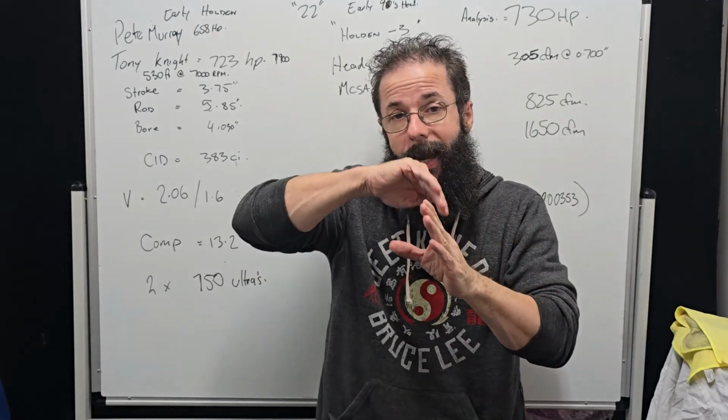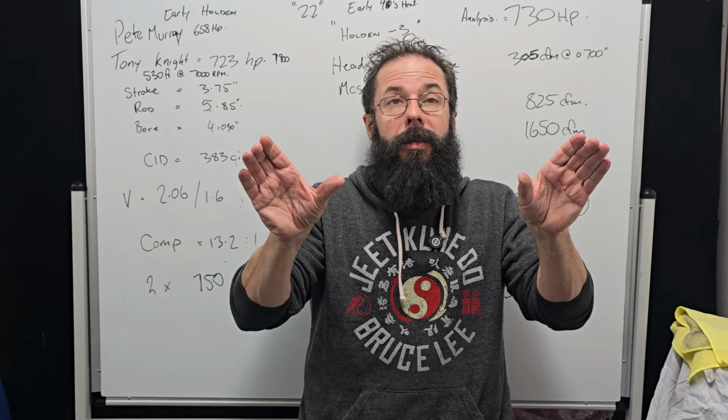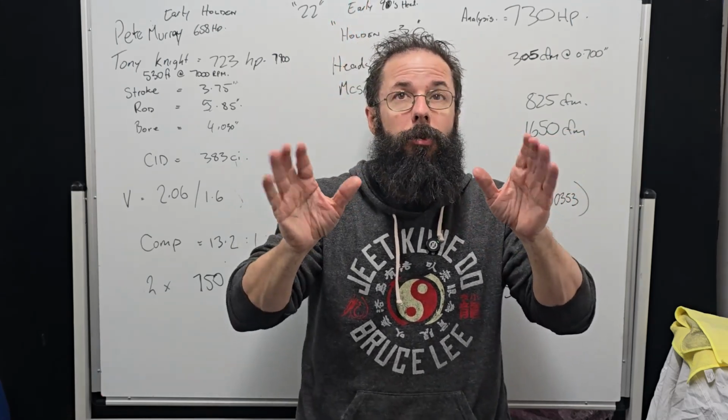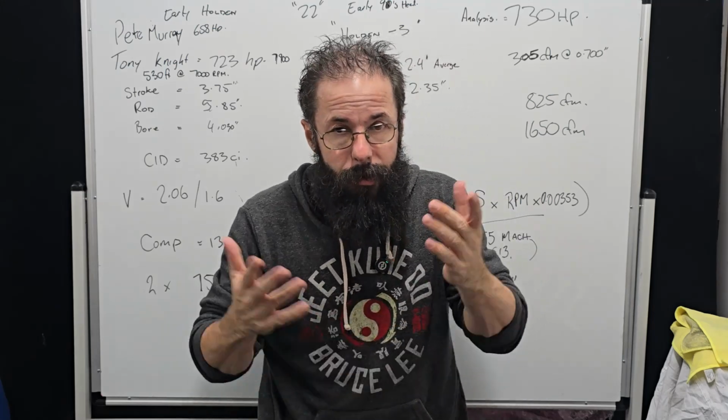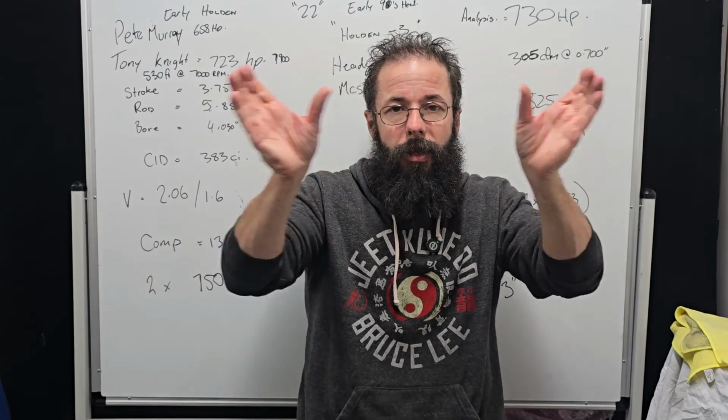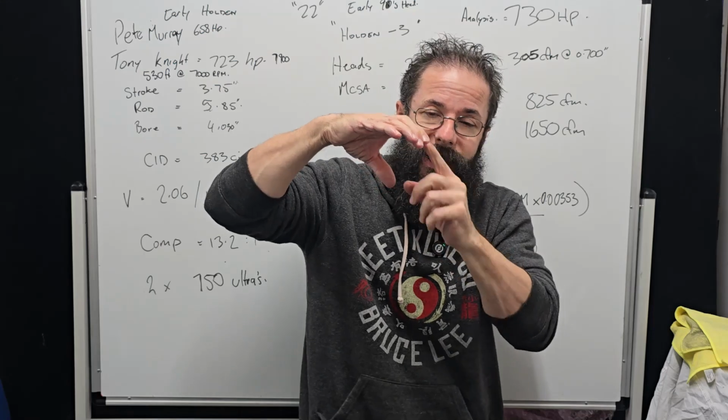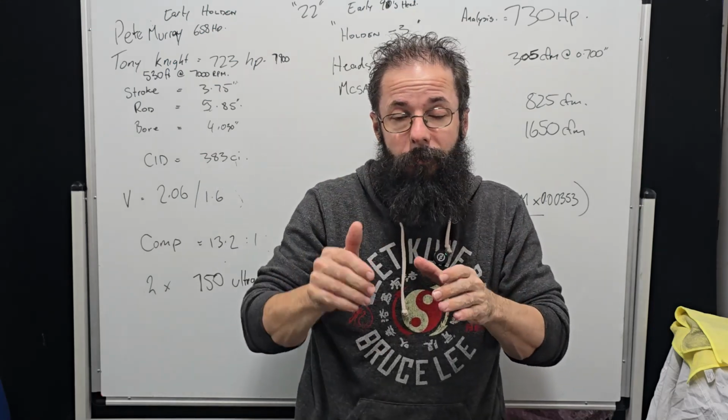I also get into radius floors. So as I move the runners apart, we have a horrible signal. And I think Darren talked about split carbs, which a lot of the guys got into, and that's so they could get the bore center over the runner for even better signal.